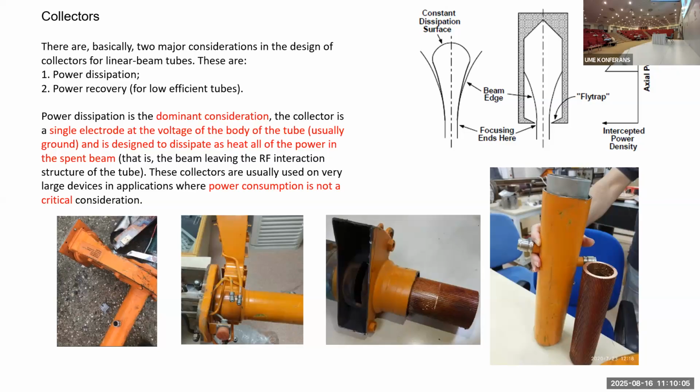Its surface is corrugated. You can see lines in here to increase the surface for cooling down. And after that there's a water jacket. And this is the cooling water input and the cooling water output on the other side. Then it's a simple, non-active, passive cooling.